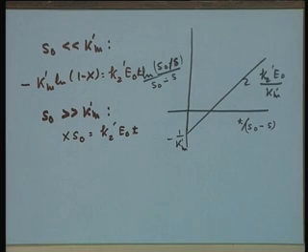Now, if the ratio of Km to S0 is very small, you will hardly incur any error if you assume it to be a first order. You will see, when we go on to consider mass transfer and more complications along with the reaction kinetics, we will tend to approximate our reactor performance in either 0 order or first order enzyme kinetics, rather than making it a Michaelis-Menten equation, which might make the solution of the expressions more difficult. It can be done by numerical methods, but analytical solutions may be difficult.